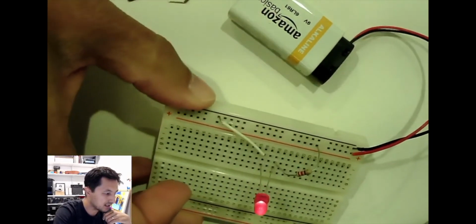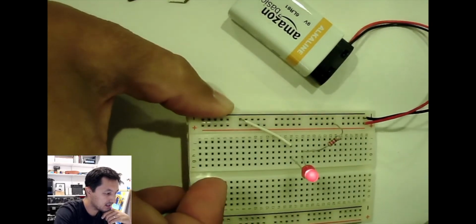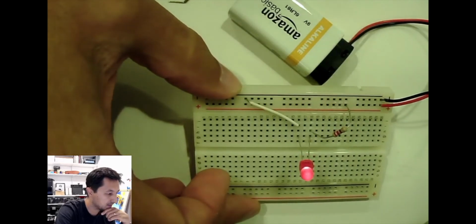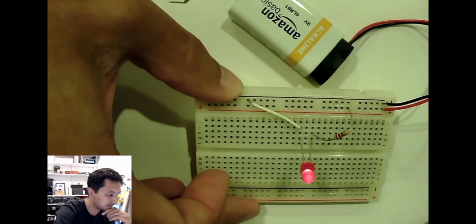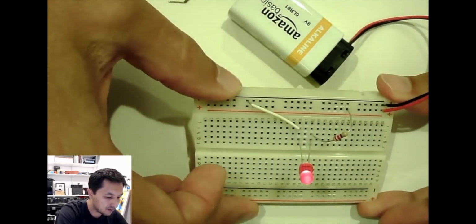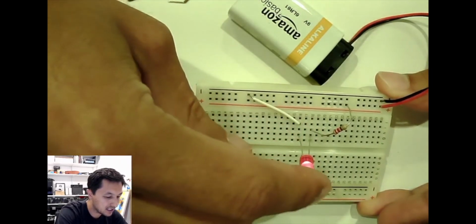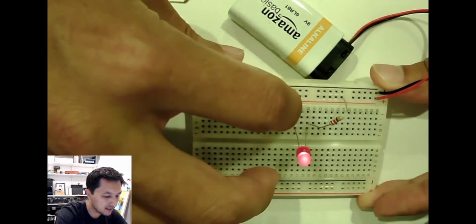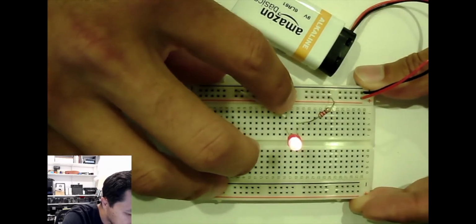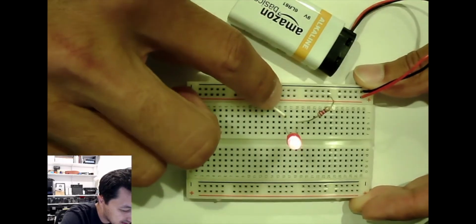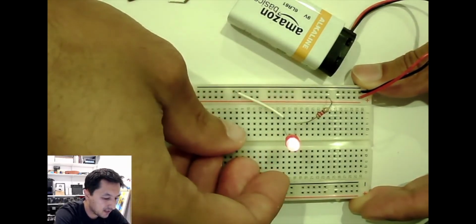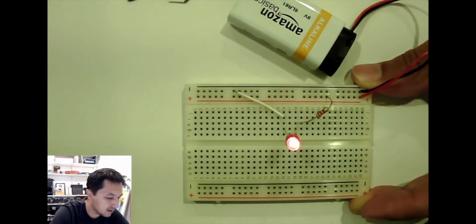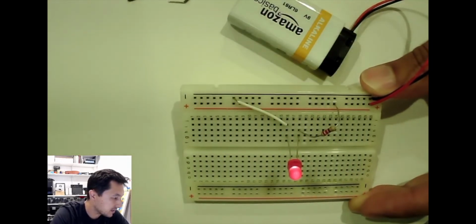This is really hard to see on the video, but the diagram is really helpful. So when doing this, I would suggest looking at the diagram for reference. The one thing that you have to remember is that this LED has to be on two separate rails. These are all numbered too, so the long side is on 18 and the short side is on 16. If they were on the same rail, then that wouldn't work, because the positive side and negative side would be on the same rail. So those sides have to be separated.